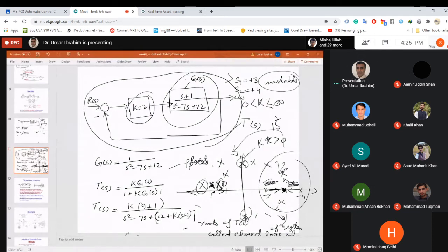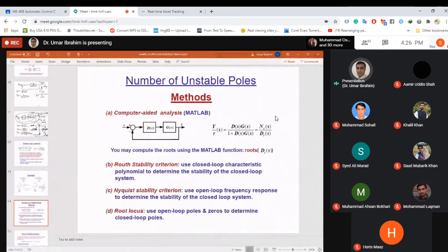For a closed loop system with variation, such as a proportional controller with a variable parameter such as K, we cannot find the closed loop poles location, or it is not feasible, or it takes huge amount of time to find closed loop poles location for a variable parameter in a closed loop feedback control system if the range is a large range. Okay? For that reason, we study Routh stability criteria.